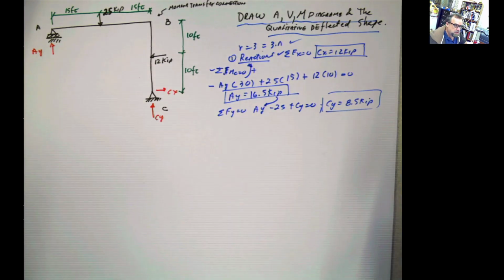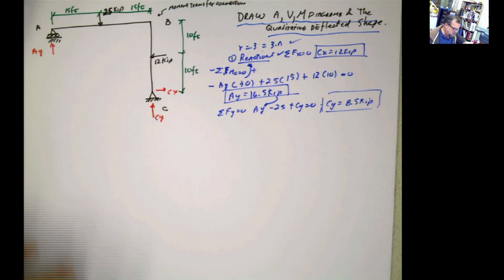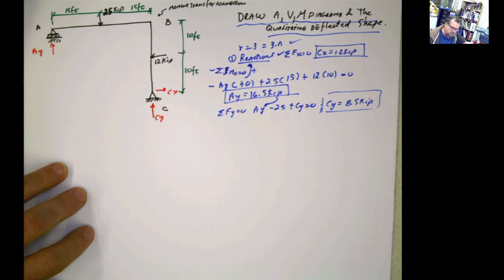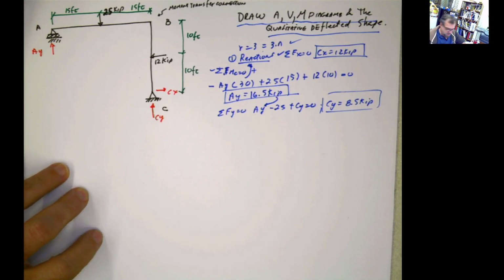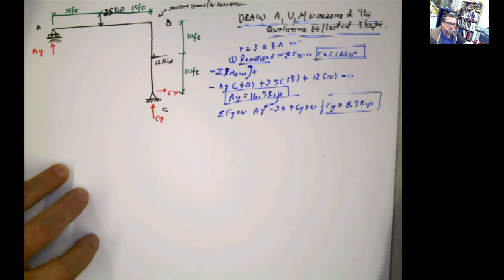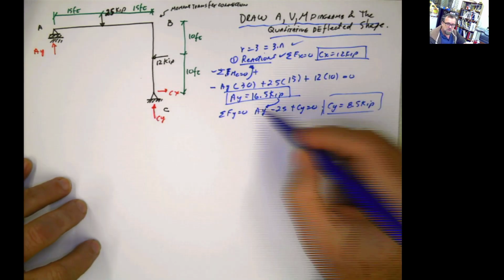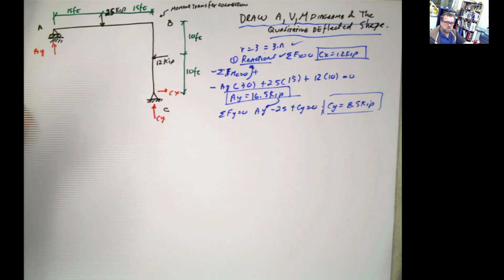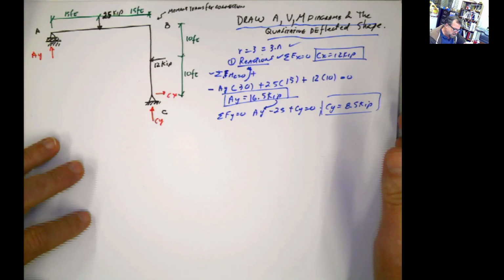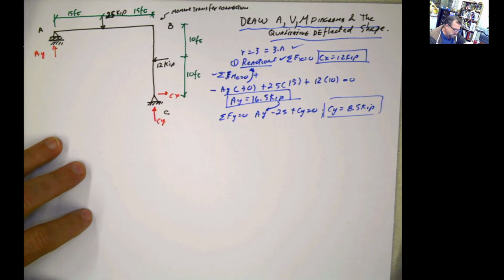Okay, if you don't verify the reactions, everything is going to be wrong. So you can do a quick verification. And how do I do a quick verification? You just do the summation of moments about any other point, put in all the values of the reactions that you calculated, and that has to be 0. For this particular case, you can take moments anywhere.